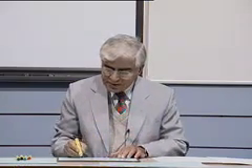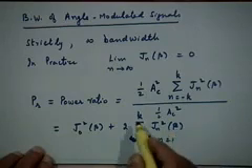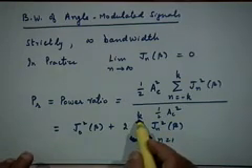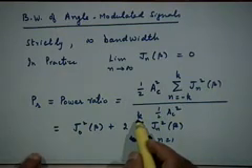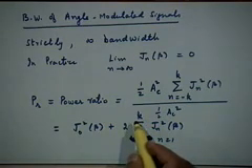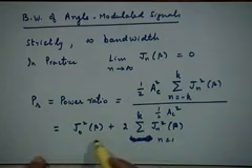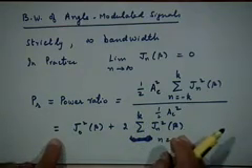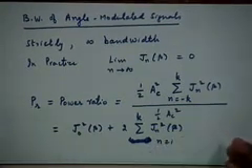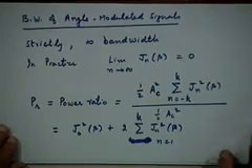Empirically it is found that for a given value of β, if you choose k to be equal to β plus 1, just one more than the value of the modulation index, that value of k would lead to this being 0.98 or larger. This is something that you look at empirically from the table of Bessel functions.